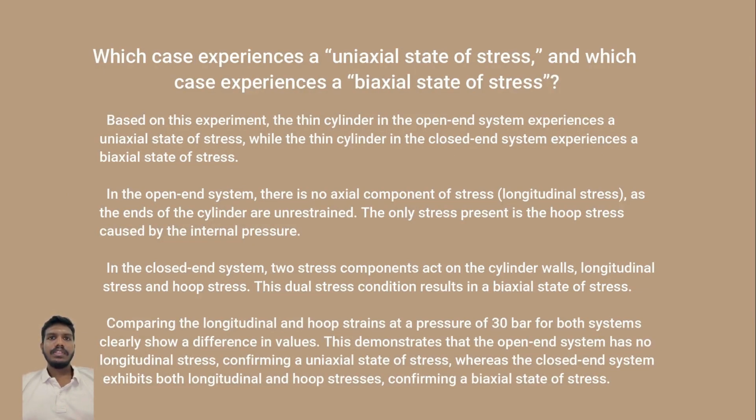Second question: which case experiences a uniaxial state of stress and which case experiences a biaxial state of stress? Now let's look at the stress states of each case. The open-ended condition experiences a uniaxial state of stress. This is because the cylinder has no axial restraint, meaning there is no longitudinal stress. The only stress present is the hoop stress caused by the internal pressure.